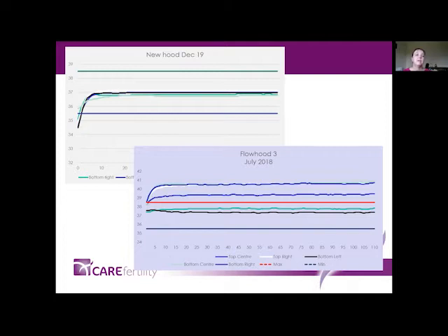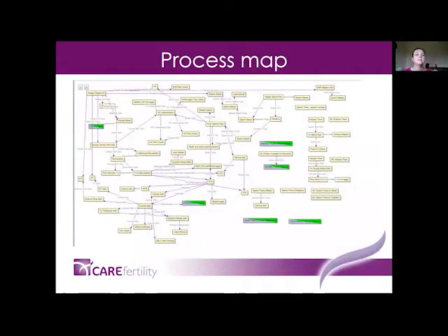But you can see on the left-hand side, this was the validation that we did from the temperature mapping from the work area that I showed you previously. And you can see you can alter each of the heated elements within the work area separately. So you can get all of the heated elements to exactly the right temperature. So the whole of the work area is usable space.